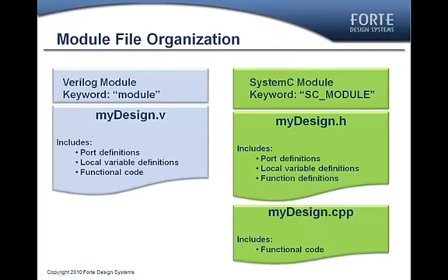Thankfully, the most basic top-level encapsulation construct in both SystemC and Verilog is called the module. In the Verilog language, the module keyword is actually module, and in SystemC it is SC module. Before we dive into a concrete example, let me first cover a couple of points about the file organization for modules. For most simple modules, like the one we are going to look at today, Verilog designers will put the entire module in a single file.